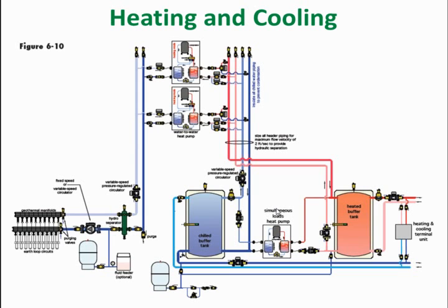And then the example in Hydronics 9 is we've got that in there, and we're showing both of those COP being 4 for those 2 heat pumps. By putting that third one in there at the bottom run simultaneously, you do the math on that and you get that up to a 7.0 COP. So that means that your heat pump is really creating 7 times the amount of energy that's put into it. The electrical energy that's going into it is coming out of that. So that's a really unique way to leverage that application. Of course, a little bit more piping, a little bit more complication, and a little bit more cost involved in that. But just something to get you thinking about there.